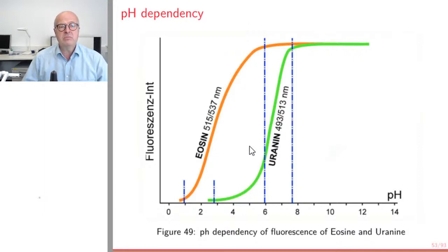I might give you a certain case, describe the case and say we have low pH, or just mention it by the way, and you should then be able to remember that and choose eosine, because it's the better tracer under these circumstances. It's not as efficient as uranine. It doesn't have the same detection limit, but it is more stable, more conservative, more ideal under these conditions.